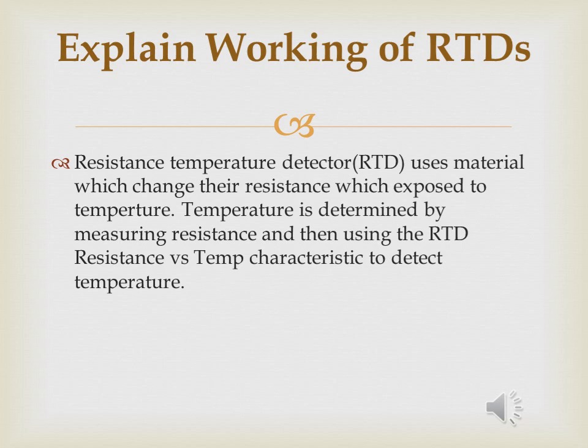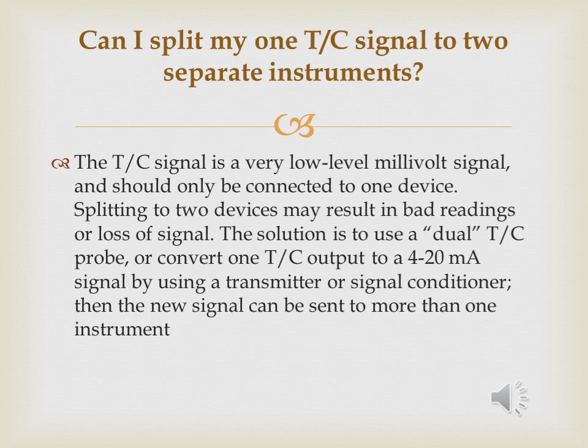What is field bus? Field bus is a general term for a digital-only, high-speed communications protocol. The key attribute to field bus communications is higher speed communications with the possibility of addressing multiple transmitters all on the same field wiring.